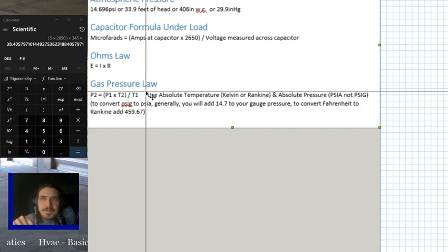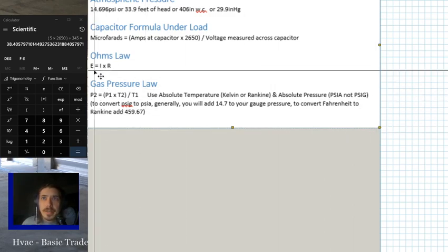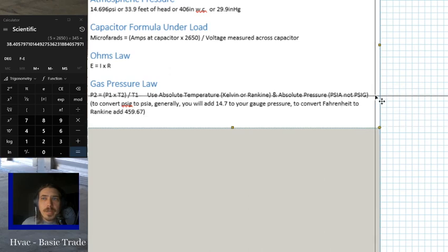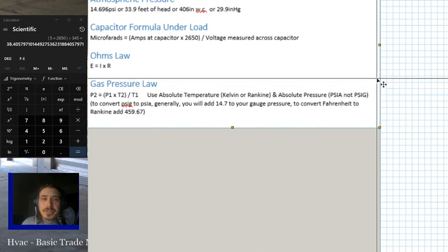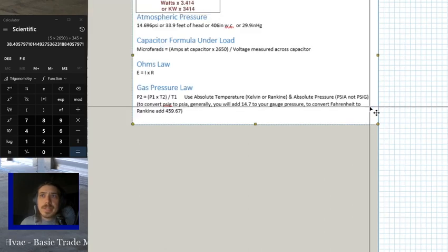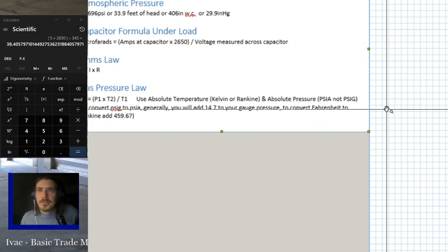All right. If you've got that situation, your pressure drops. It's 80 degrees, you put the test on, it's 550 psi. You come back the next day and it's 30 degrees cooler and the pressure dropped. And you think, well, nitrogen doesn't change pressure with temperature, so I got a leak. No. That's not what's necessarily going on. You need to determine whether or not you actually have a leak. So, this is how you do it. This right here is how you make sure whether or not you have a leak or your pressure just changed with temperature. So this one's going to take a few more steps.